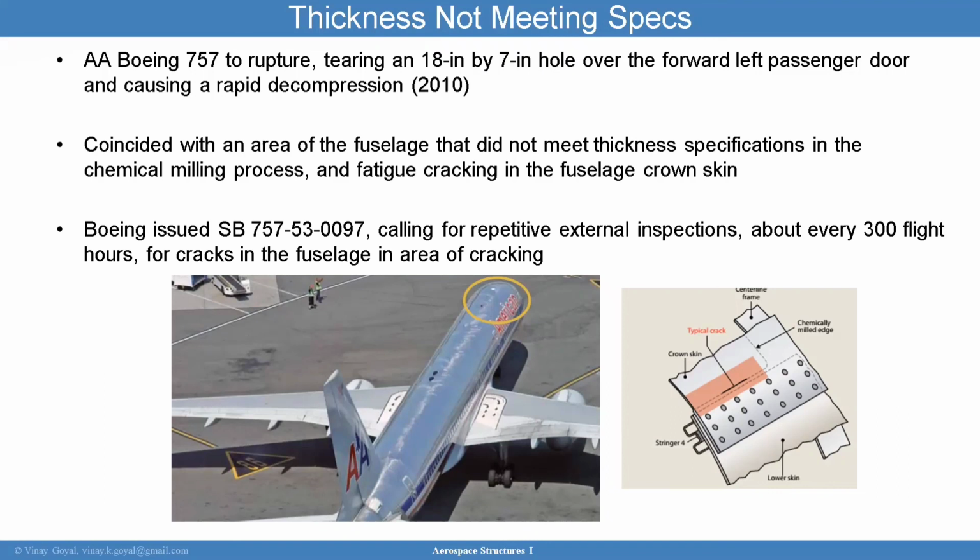FMEA. Exactly, right? If I'm the engineer, I could have stated in the design FMEA that if we are unable to meet the dimensional specification or the tolerances in this part, this could happen. And because this could happen with this level of severity, this is the action that I will take. And maybe the action was for me to be very clear on the drawing about what the tolerance should be for the finished part. Very important to take that into consideration. For the finished part, it has to be within these tolerances, because if it's not, this can happen. And because I don't want that to happen, I'm going to take this action, right?